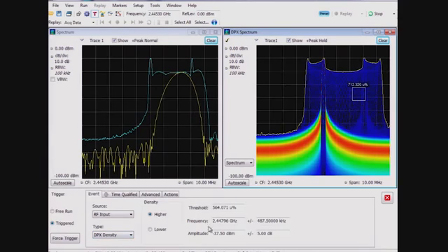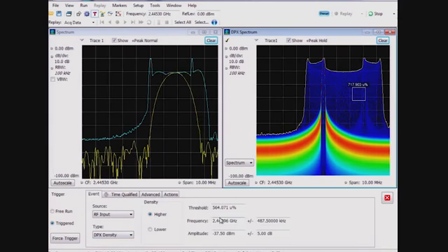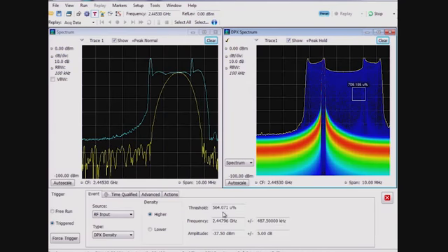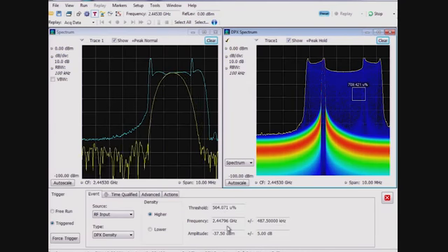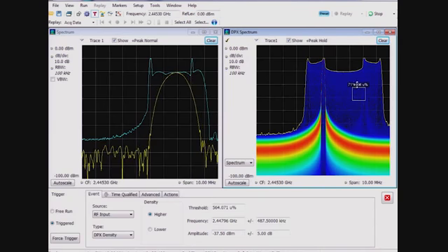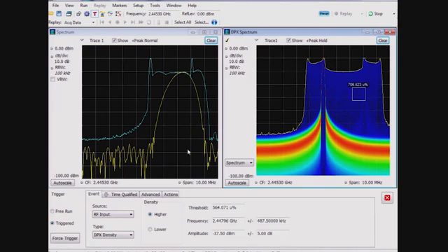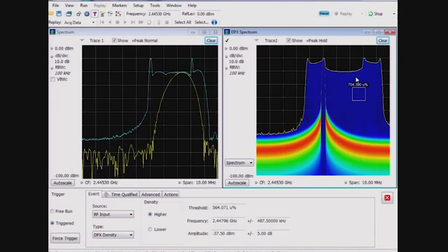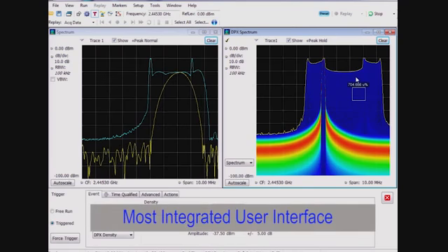Now, this signal density is different from that measured in other spectrum analyzers because it's measured over a period of time. Next, the trigger threshold is set to a level just below the measured signal density over time. Last but not least, the instrument's trigger was turned on to start the triggering. This DPX density box is adjustable by the user.